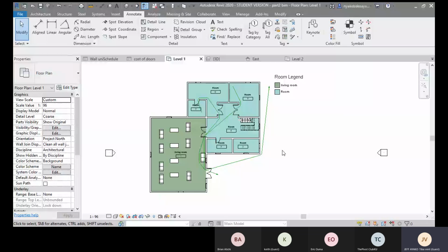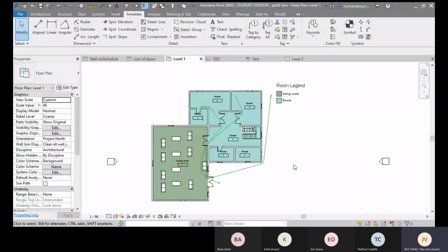All right, so now we want to do energy analysis. Whenever you are heating a room, it's being warmed up and all of that stuff. So that energy is distributed not on a surface, but on a volume, because a room is a volume. Once you do the setting for your rooms here, currently these rooms are resting on the surface. So you need to change that.